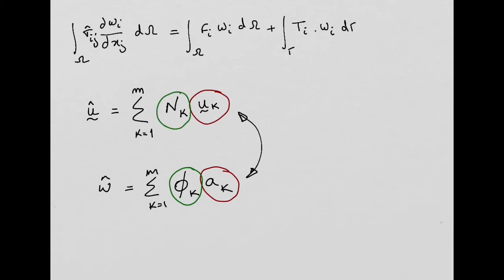So they are still shape functions, and they will depend on the type of finite elements you are going to use. For example, if you look at 2D finite elements, if you are going to use triangular elements, you will have a well-defined set of shape functions. If you are using a quadrilateral element, you will have also a different set of shape functions, very well defined for that type of element.